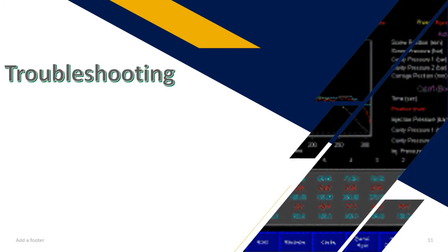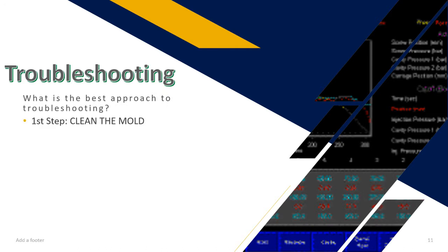So one of the best ways to avoid becoming a button push cowboy is, first step, you're going to clean the mold. You don't start making changes to the process. You're going to assume that a validated process that's run at minimum of 8 hours, good parts, zero scrap, high efficiency. So you need to figure out what changed. So first thing you do is clean the mold, make sure that it's properly greased, make sure that all mold components are functioning properly.